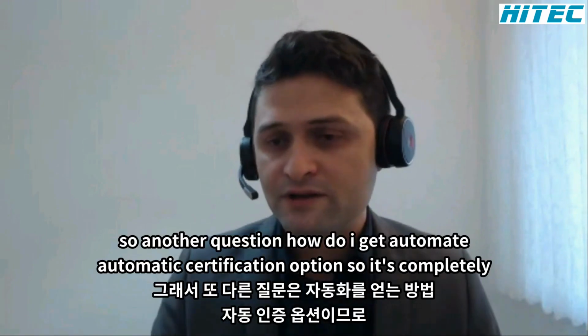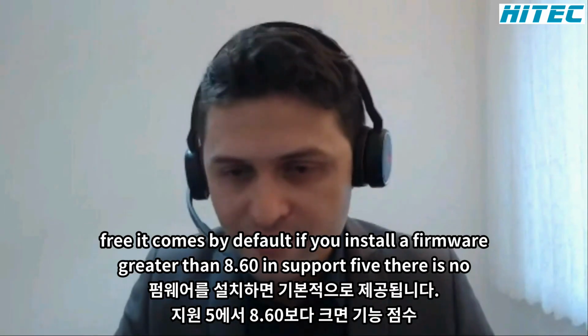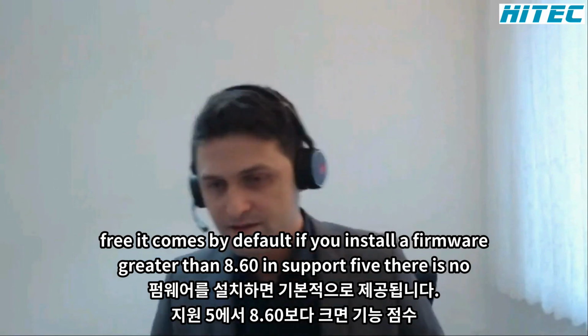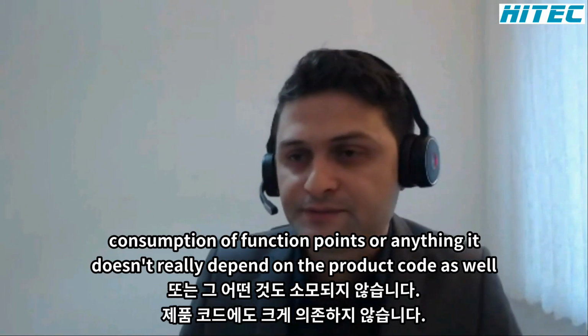Another question: how do I get the automatic certification option? It's completely free. It comes by default if you install a firmware greater than 8.60 in SIPROTEC 5. There is no consumption of function points or anything. It doesn't really depend on the product code as well.